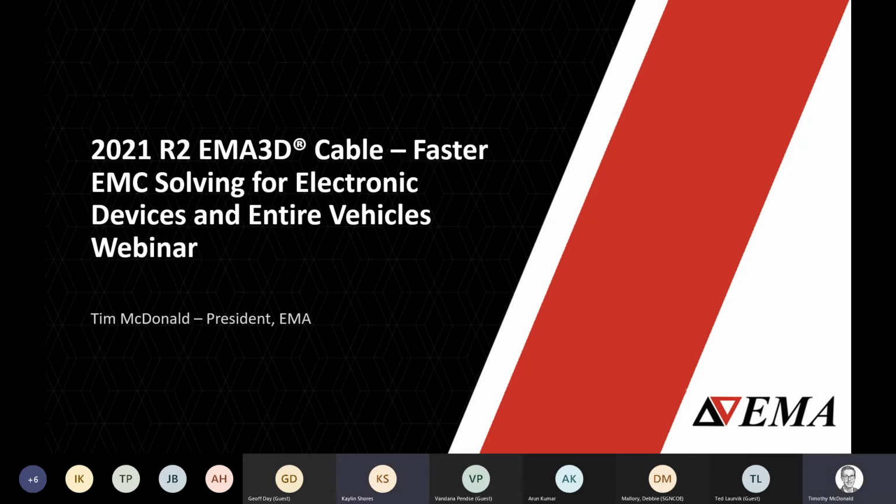Okay, next question is from Sean. How scalable is the voxel mesh for small details on a large model? Yeah, there are many ways to handle that. You can have an entire aircraft with extremely small voxels, which is computationally expensive and may require a multi-core cluster. We also have subgrids, so we can zoom in on some small parts of the aircraft, mesh them to a higher resolution, and combine them in an aircraft model that's more coarsely meshed.